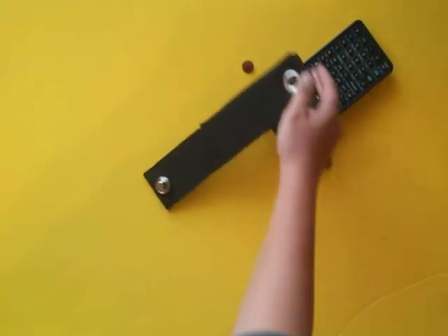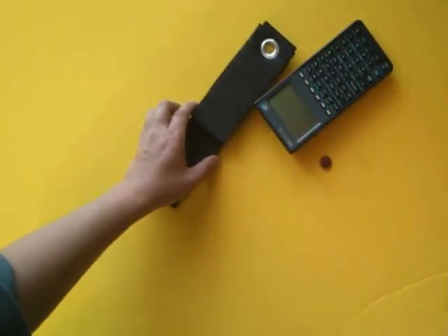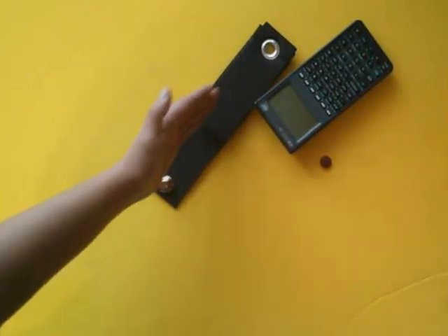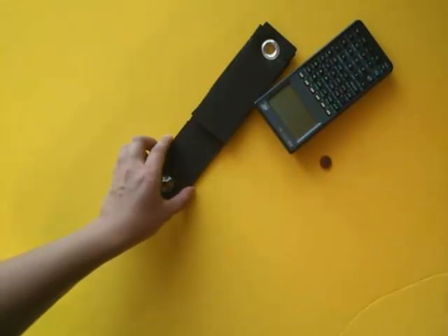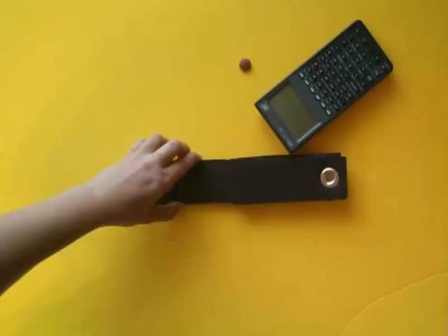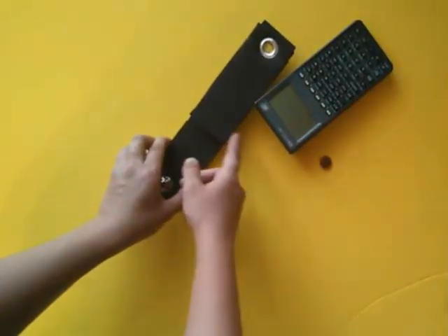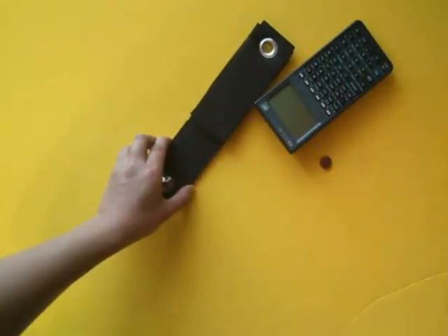Then I'm going to move the link to the other side of the obstacle and check what angle it's at when it collides with the obstacle on the other side. Here it's at about 45 degrees. This tells us that the manipulator will collide with the obstacle anywhere between 5 and 45 degrees, regardless of the angle of theta 2. So let's go draw that in configuration space.